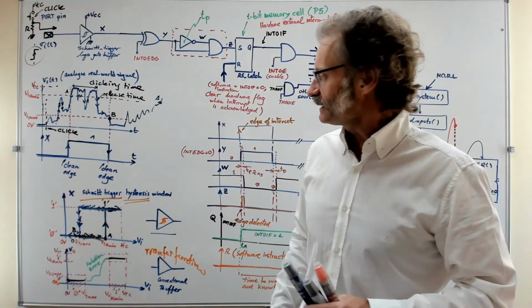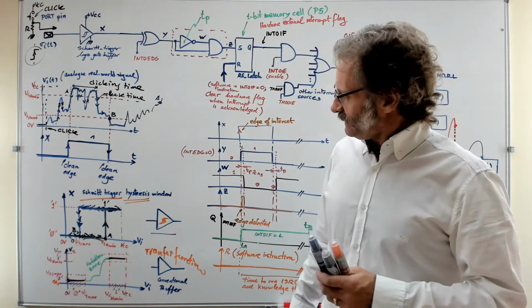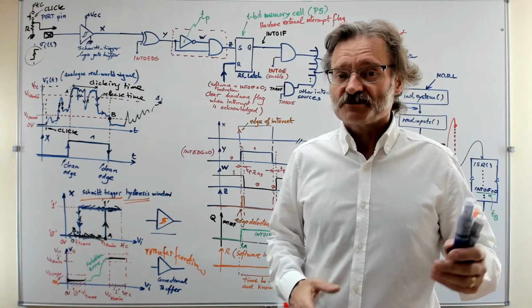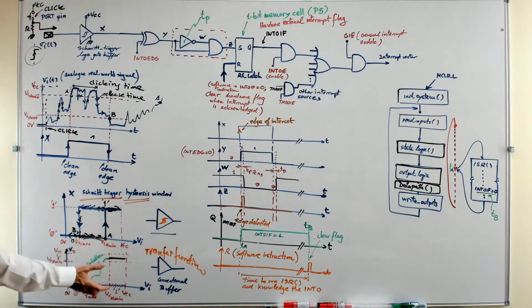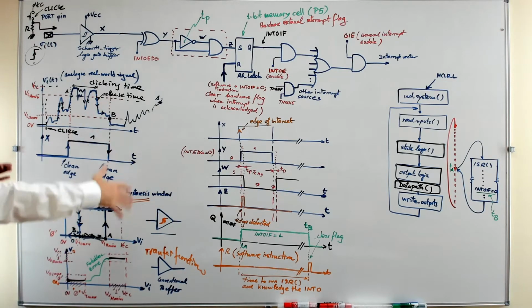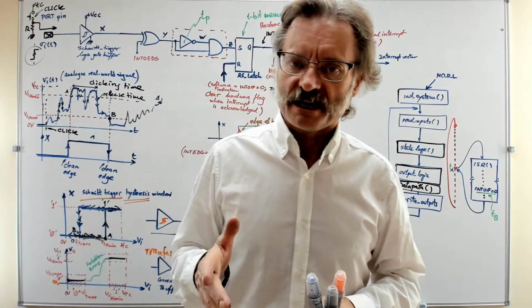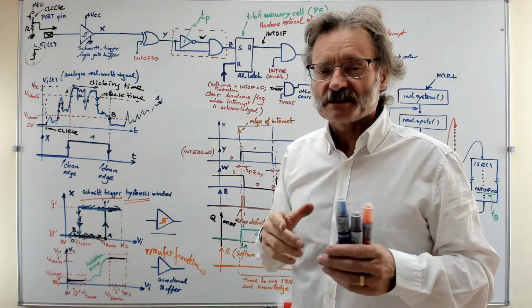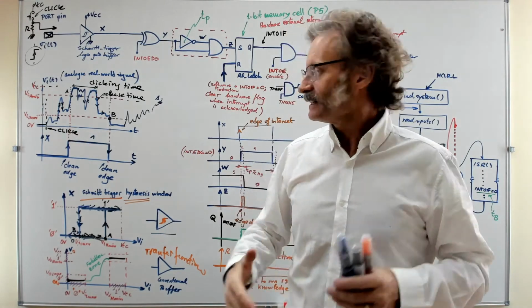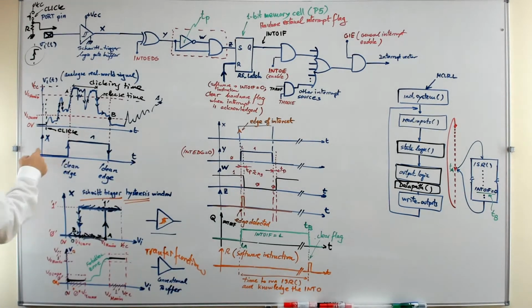It has an internal circuit that is based on this idea of a Schmitt-trigger hysteresis, and it is possible using positive feedback to get this kind of window that solves this complication of the forbidden zone. Now that's good to know, okay? So by means of this device, when you click, you can imagine you have this kind of debouncing circuit to get rid of bouncings and everything else, and you get something important here. It's a clean digital signal.